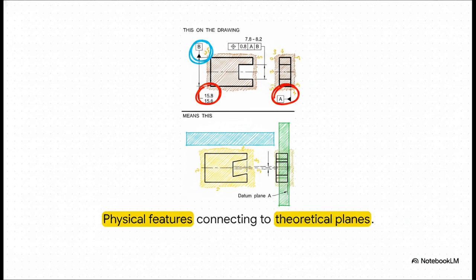You can see exactly how this relationship plays out on a standard drawing callout. Notice how the physical datum features, like the right face or the top face, are what actually get tagged. In reality, those imperfect, slightly wavy physical surfaces are brought into contact with perfect, theoretical datum planes. We interact with the physical part, sure, but the tolerance zones, those are established by those perfectly straight imaginary boundaries.